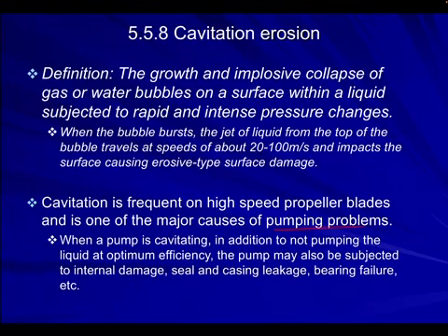So we looked at this. So when your pump is cavitating, in addition to not pumping the liquid at optimum efficiency, the pump may also be subjected to internal damage, seal and casing leakage, bearing failure, etc.